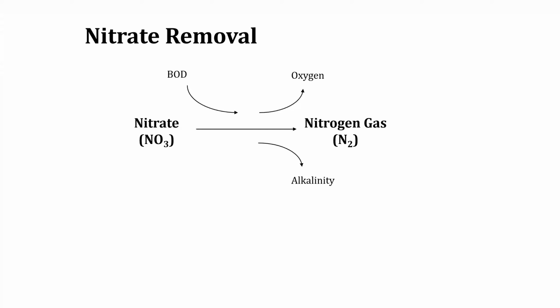That's the bad news. The good news is this: when you implement nitrate removal, if you were not removing nitrate before, you were removing ammonia and kind of stopping there. Now you're going to start removing BOD with all that extra oxygen you put in to create the nitrate. The organism is going to breathe that, and that's going to reduce your overall electric demand in most all cases. Doesn't really put oxygen into solution, it puts it to use. And then it also brings back some of the buffering.